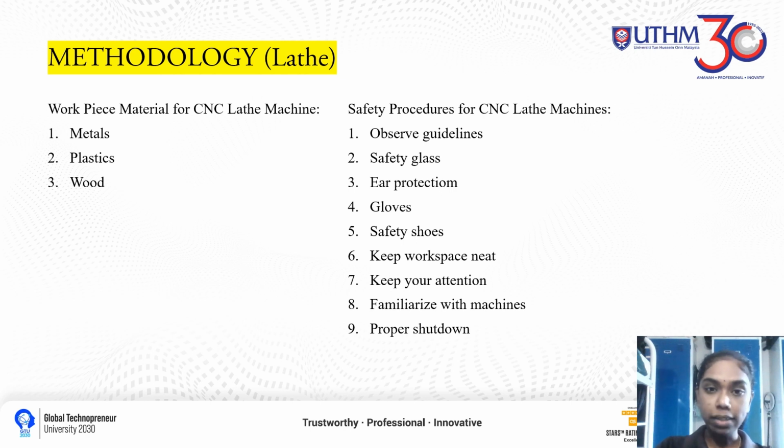Apart from that, safety procedure for CNC lathe machine is also very important, such as observe guidelines, wear safety glasses, ear protection from noise, gloves, safety shoes, and then keep workspace neat, keep your attention, familiarize with machines, and proper shutdown is very important.